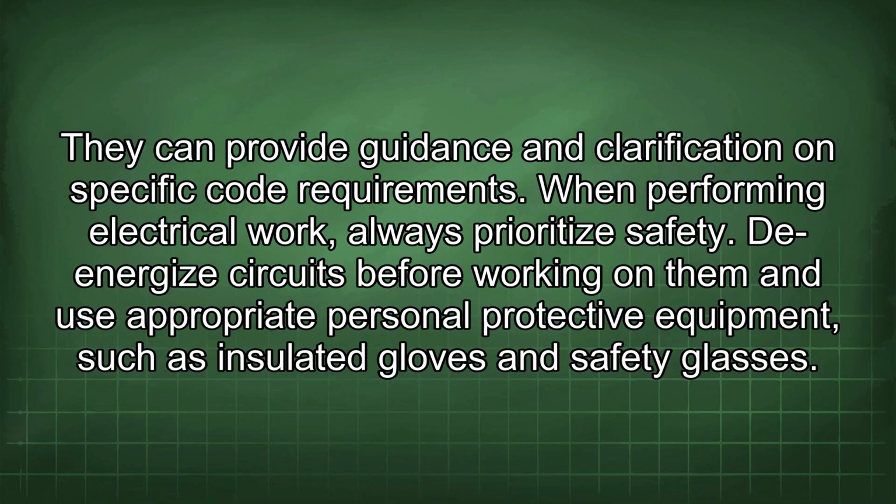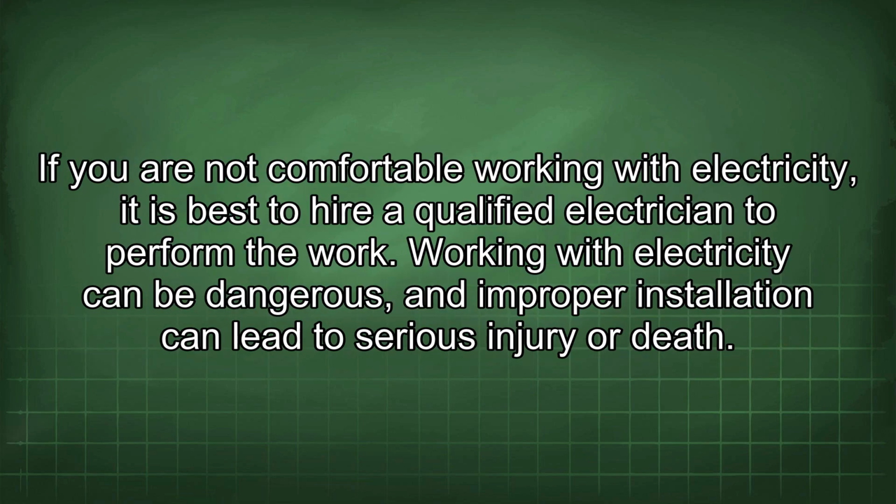When performing electrical work, always prioritize safety. De-energize circuits before working on them and use appropriate personal protective equipment, such as insulated gloves and safety glasses. If you are not comfortable working with electricity, it is best to hire a qualified electrician to perform the work. Working with electricity can be dangerous, and improper installation can lead to serious injury or death.